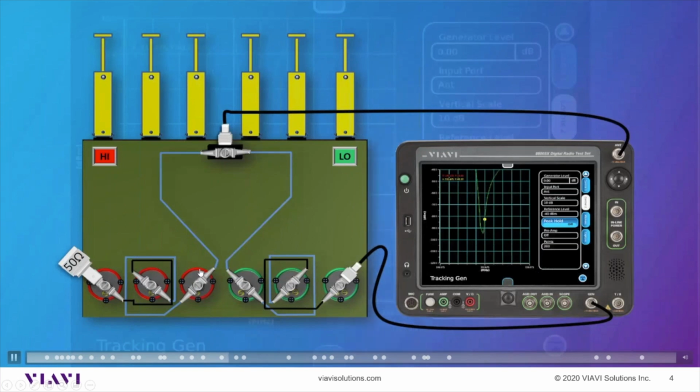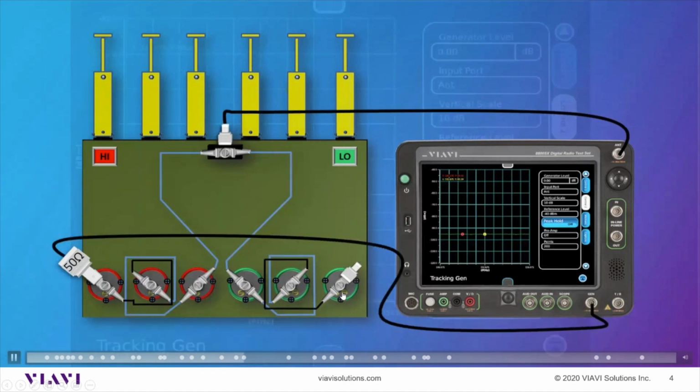And now we're switching over, and I'm down on the tuning caps, adjusting those to get the notch down, to get it on frequency and as low as possible. Like I said, we put those cables back on, and it moved our notch a little bit. So we're just going through and adjusting our capacitors to do that. And we'll move along here a little bit.